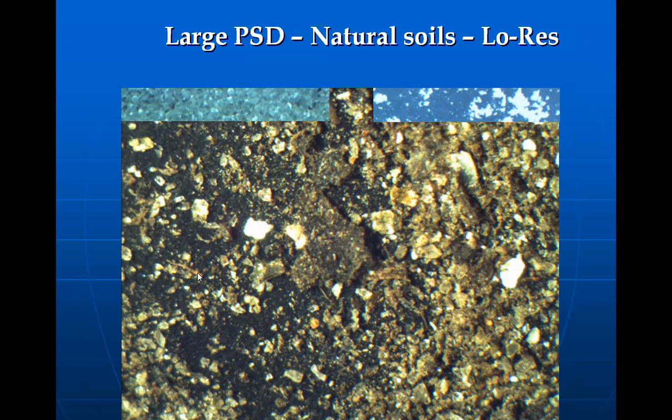There's little pieces of organics, which is probably part of a root here. But notice the angularity of the particles. There's a mica grain probably right here. There's mica all over this slide. There's grains of feldspar, which have a distinctive crystalline shape. But the silica that is here is not clean. It's not shiny. It's not easy to see through. So this soil had a low sand content.